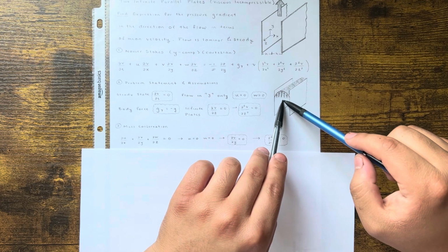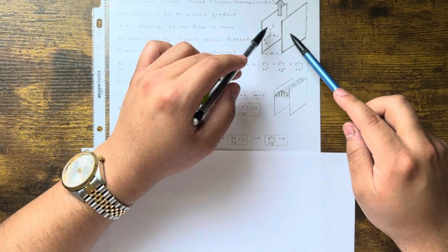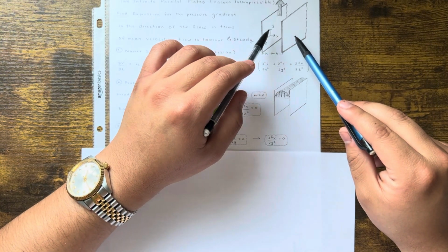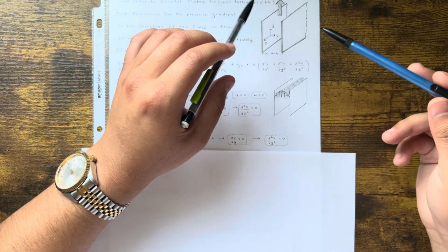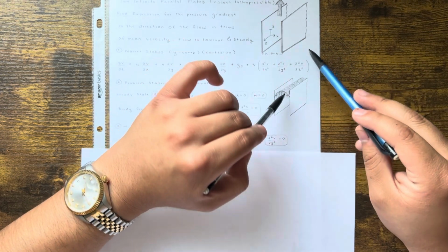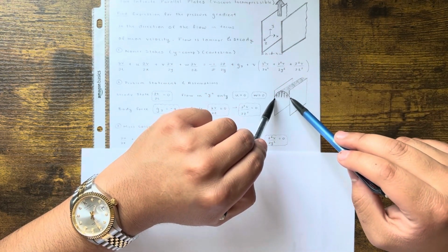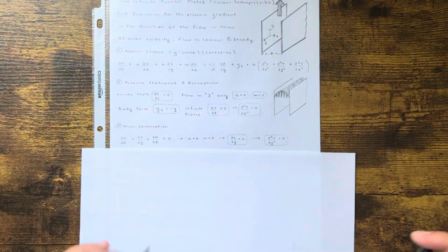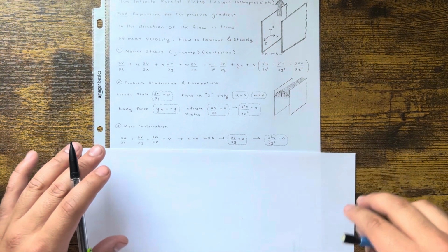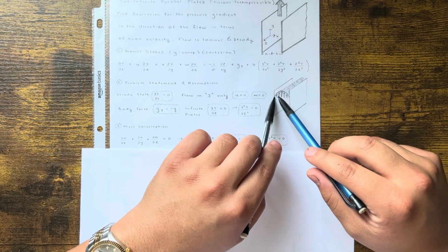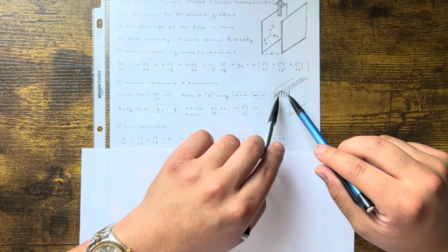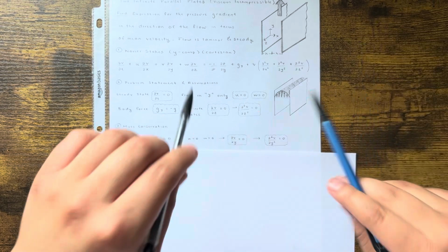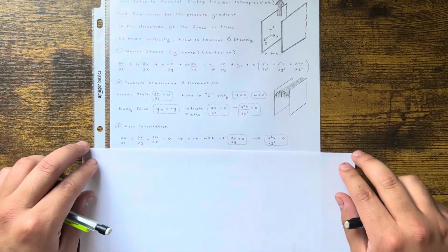So this was just pure intuition. I'm thinking about it, because at the plates, you're going to have no slip. So the fluid wants to stick to the walls. At the center, it's not sticking, so at the center, it's the highest. And because of the no slip, it forms a parabolic shape. So I was just using intuition, understanding what the flow is going to look like. But technically, I just drew this just so you guys could see it. You don't even need to draw this on your problems. This is just so I can explain going into the paper. That's what it looks like.